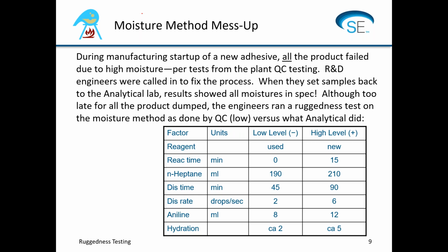So somebody got the bright idea that they would take that off-grade specked resin and try to slowly work it back into the resin that they were producing, but it was like the cat in the hat. As they put back the resin that had the specks in it, more specks were created, and that didn't work. So they were always trying to come up with some kind of a scheme. And it was tricky trying to make this polyamide resin. One of the key things was they needed to keep the moisture within a certain range, or below a certain level, or it would mess up some of the functional properties of this resin.